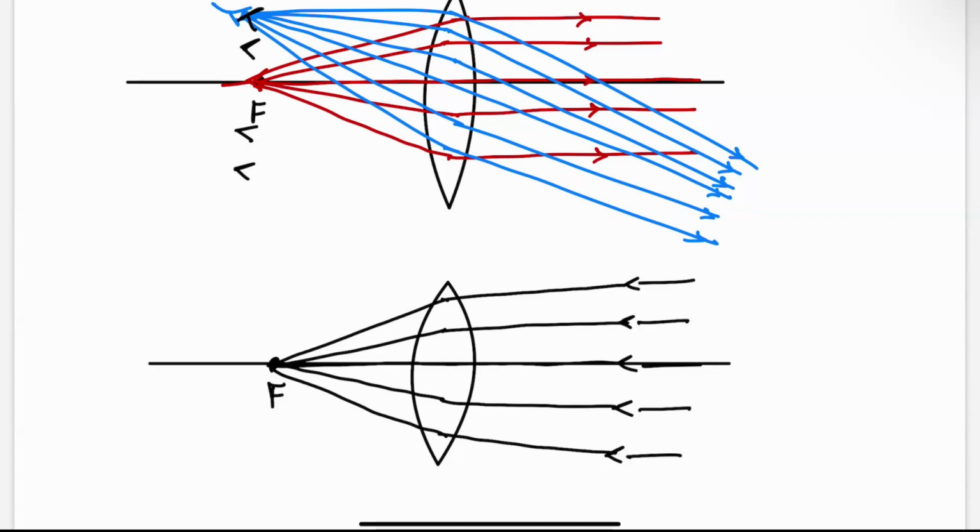But the idea behind a Rotman lens is that if I add a second parameter that I can control, let's say I can control the length of this line. Let's say I can meander it, right? So from here to here, I can meander this line and add some extra length, some arbitrary length, to each of these sections. Then I have a second parameter to control, right? So let's call this W, which is the length of that line. And I can control this lens, epsilon, right?